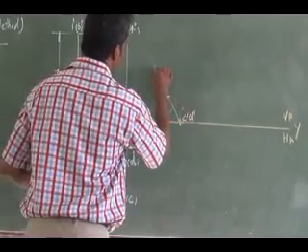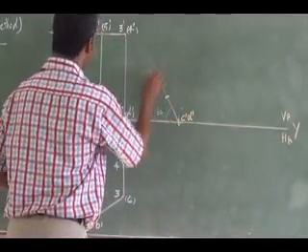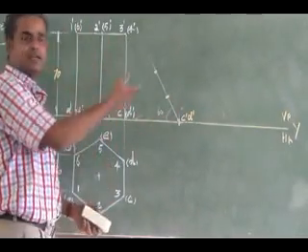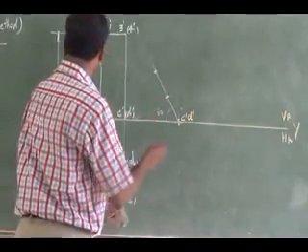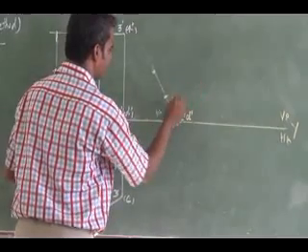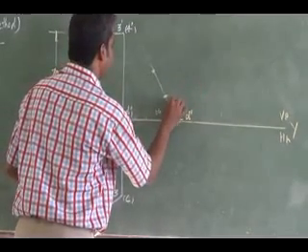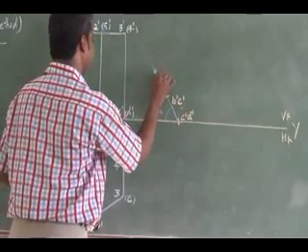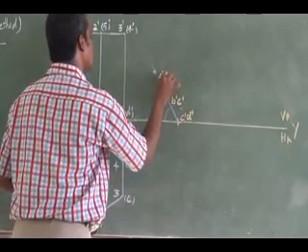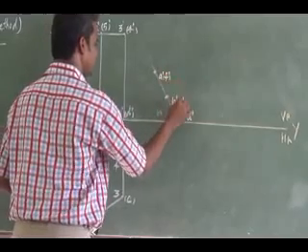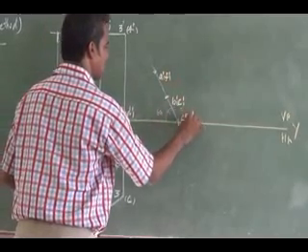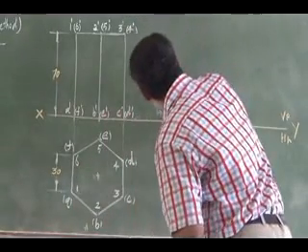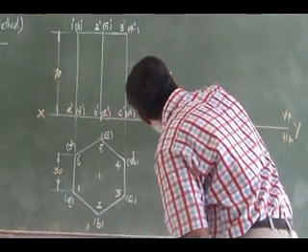Right. So these are my locations of B E and A F. Just to measure it and transfer it. This is my B dash, E dash. This is my A dash, F dash. Is it clear? I have transferred the base to 60 degree inclination.